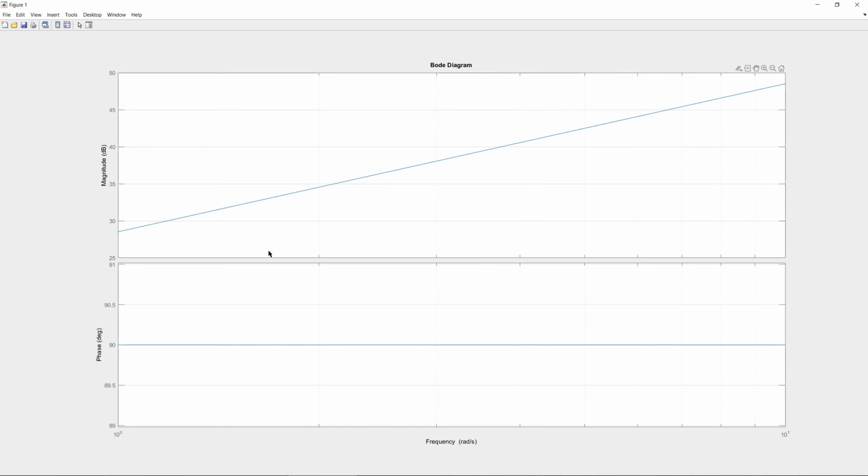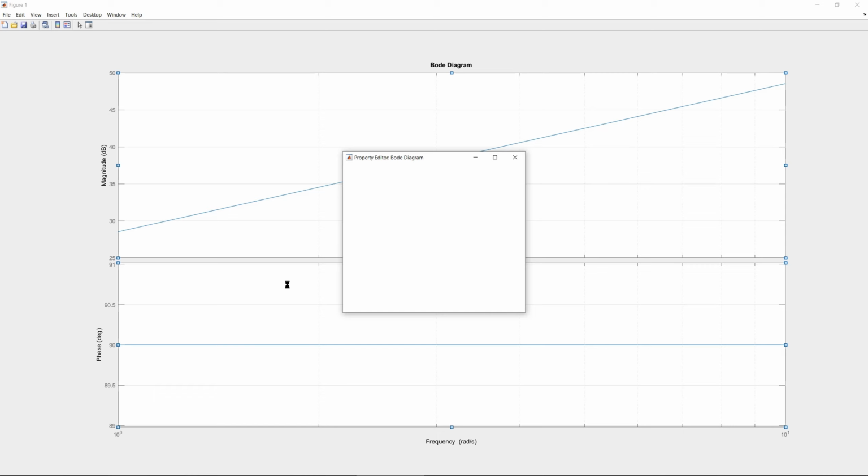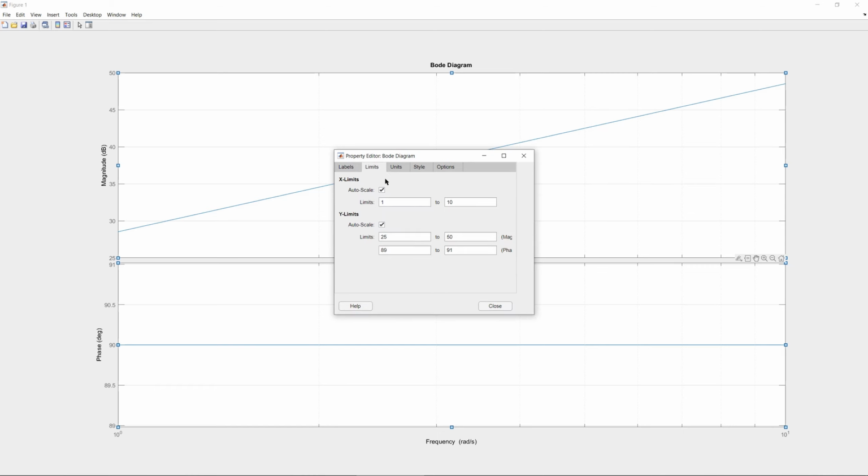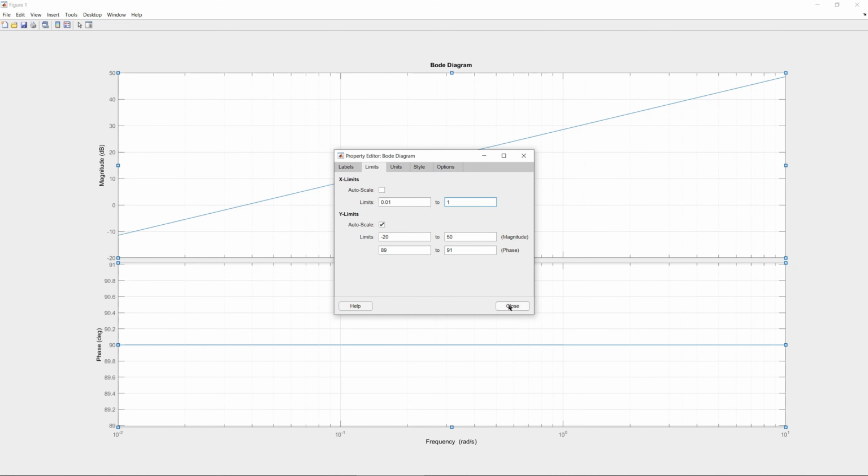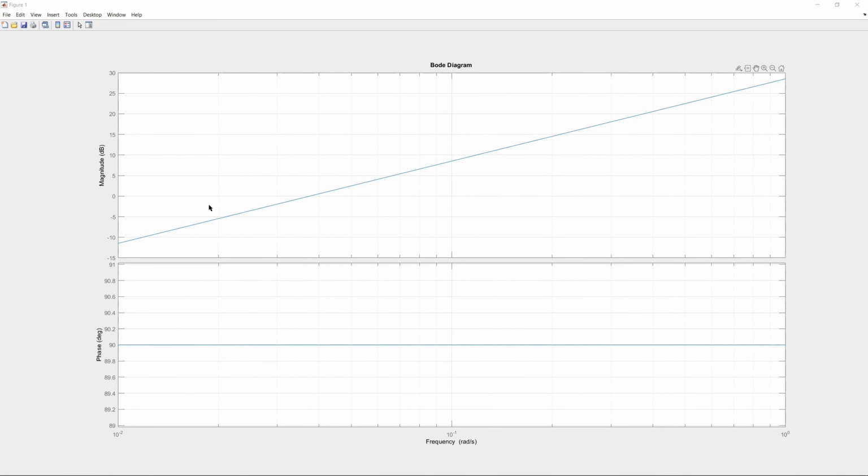And you can see here, if I now go with the frequency, you can see also the unity gain frequency in this analysis. Let me change the limit of the x-axis. So I will go to 0.01 and all the way to, you can see if I want to go to the 0 dB, it's approximately 0 dB, and then I have the unity gain frequency as we have discussed.